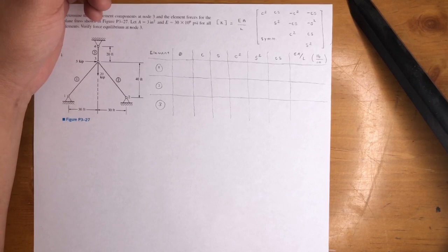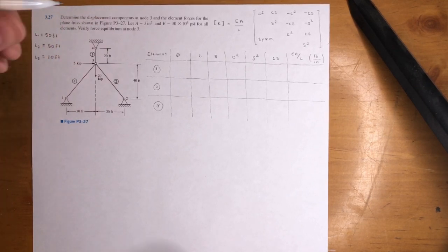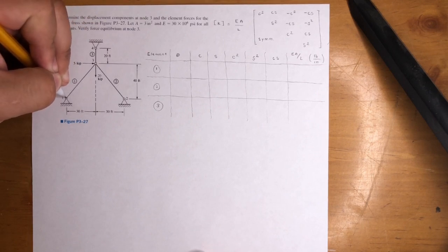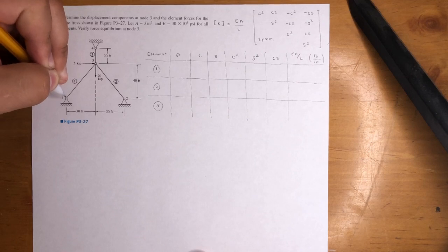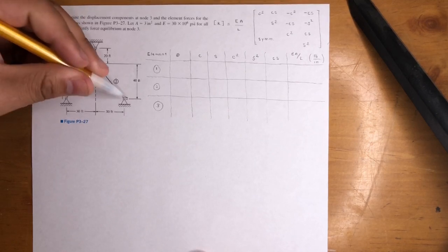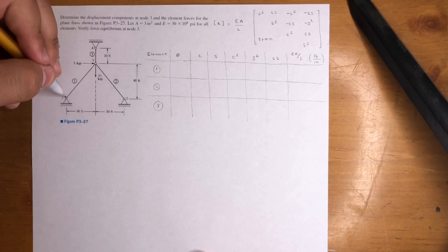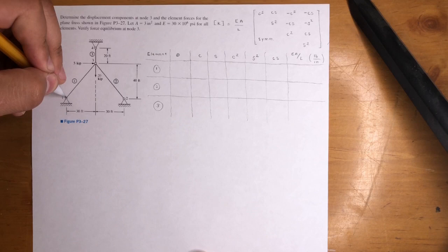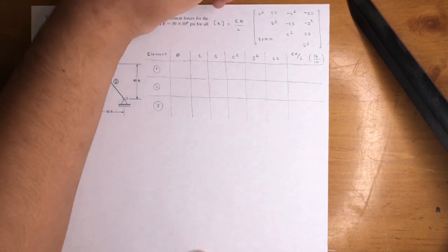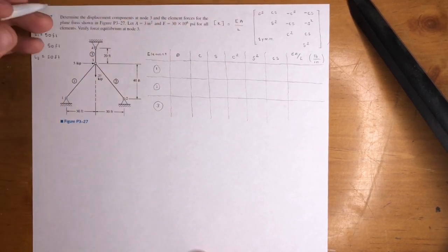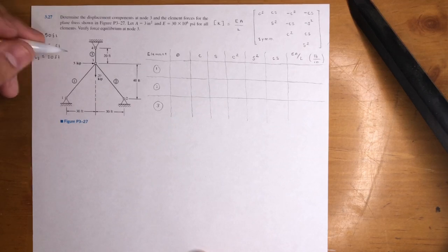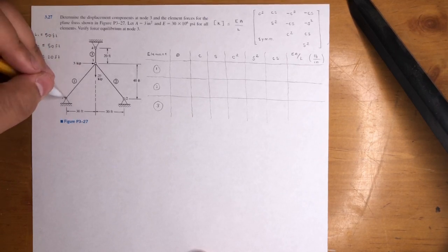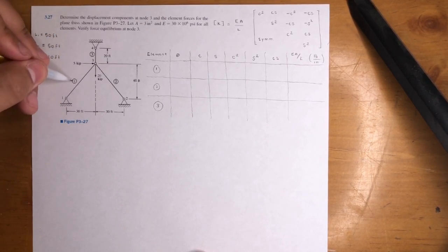So determining the angle, I mentioned it in the previous video, but I'll go ahead and do it one more time. I always stick to going from the smaller node to the bigger node. In this case, 1 is the smallest, 1, 2, 3, 4, they're all in order. So go from 1 to 3, don't go from 3 to 1. I'll show you how to do both, but just to be safe, when you're doing the matrices, it could get a little confusing once you start labeling the columns and rows, with U1, V1, U3, V3 in this case, or U3, V3, U1, V1, but always go from the small one to the big one. So let's go ahead and do element 1.